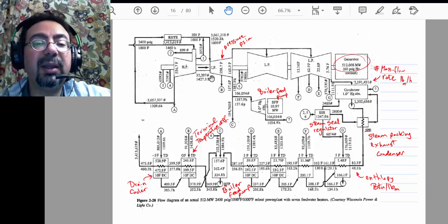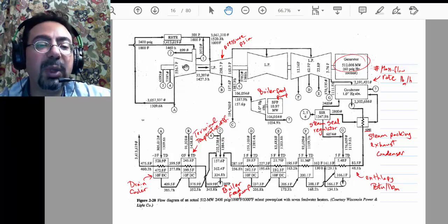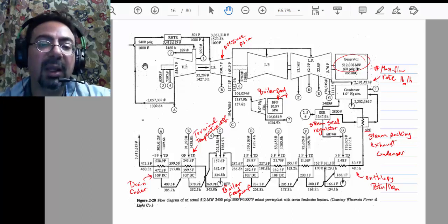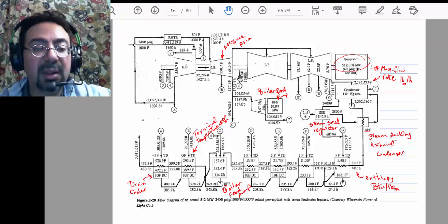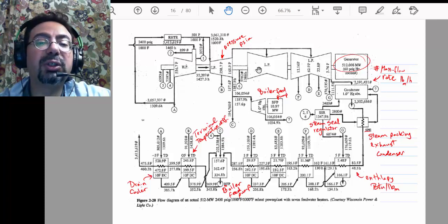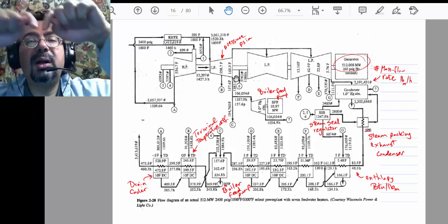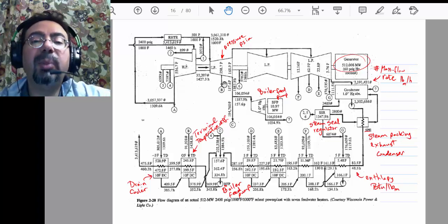See those bearings, if you go this way and you leave that way, you will generate axial thrust on the turbine. And bearings carrying axial thrust are not as efficient as bearings that do not. So by putting them back to back like this, they will cancel each other a little bit. And the same for the low pressure turbine. You make it into 2 parts, and they are sitting again back to back.